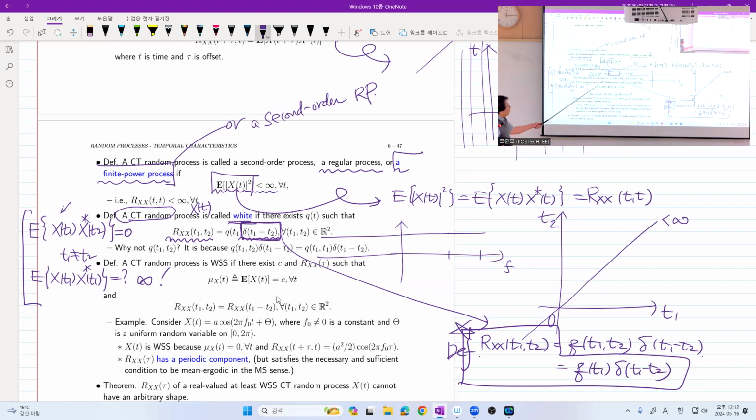And stationarity, we already defined, right? Now, let's see this example. Here, the amplitude is constant, the frequency is constant, but the phase is uniform. You've already seen this. The question is, what is the autocorrelation function of this one, and is it a function of time difference? You already know that. If you compute the autocorrelation function as a function of t and tau, you have only a function of tau.